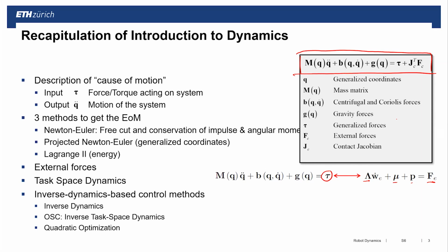So in big contrast to a position control system, where essentially the feedback controller of the local position loops tries to cancel out all the dynamics, in inverse dynamics control we try to compensate for that by this model knowledge. So ideally, if you have perfect knowledge of the model, you don't need any integrator gain. You can just feed forward, define how the system should move, and then produce the torque that makes it move in that way.